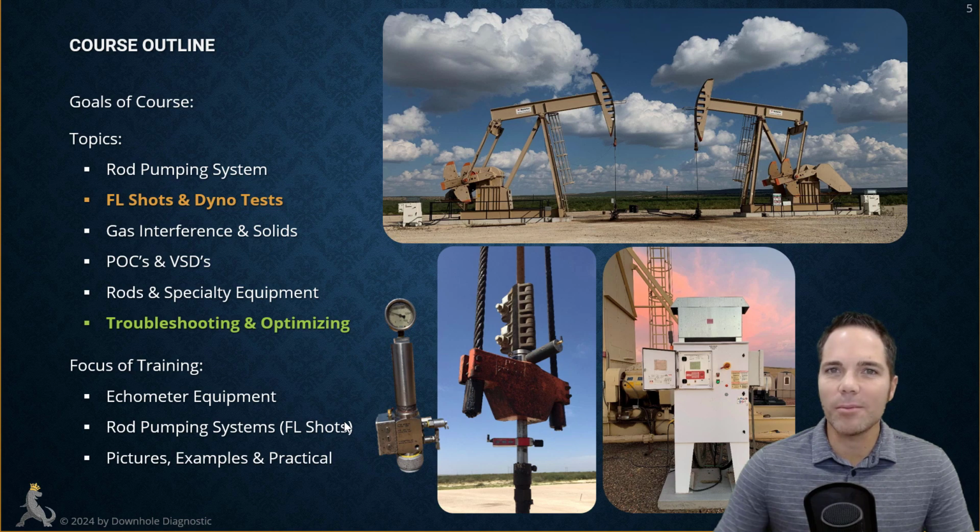Now, you might not have rod pumping wells, and that's okay, because when we talk about fluid level shots, I will show you examples from gas lift and ESP and other forms of artificial lift, and really the principles of interpreting a fluid level shot and how it calculates the distance to the fluid level are going to be the same whether you have a rod pumping well or a gas lift well or any form of well. But we are going to focus on rod pumping systems specifically because we're going to be talking about dynamometer tests as well, and this is specific only to rod pumping wells.